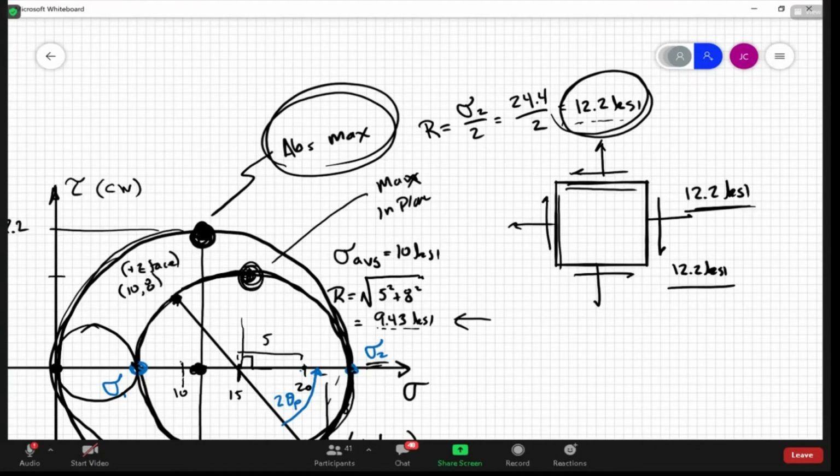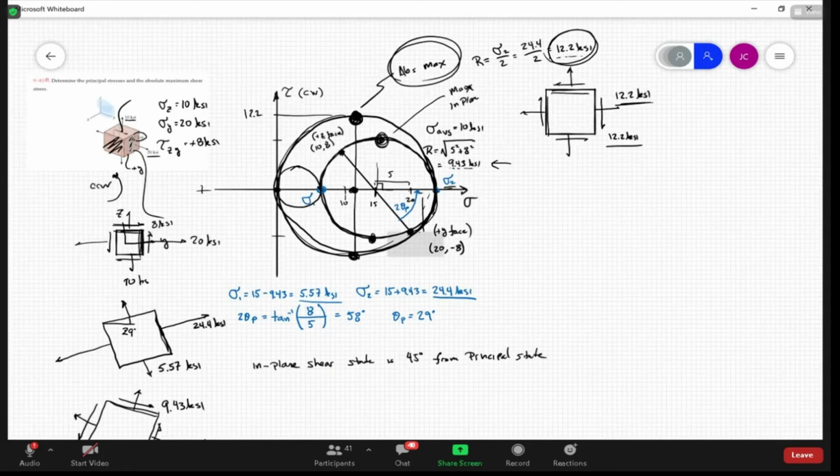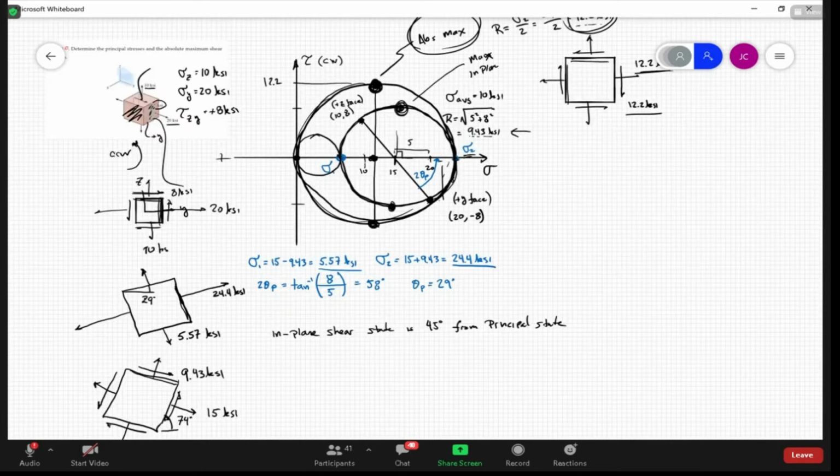All right. So again, Mohr's circle is kind of nice because you don't have to really memorize anything. The equations are just basically geometrical things, so it's pretty easy. Draw Mohr's circle. The 2 points correspond to the faces. Then we can calculate the principal values, and we can also figure out how we have to rotate in plane to get that. You can get the maximum in-plane shear state and also the maximum absolute.